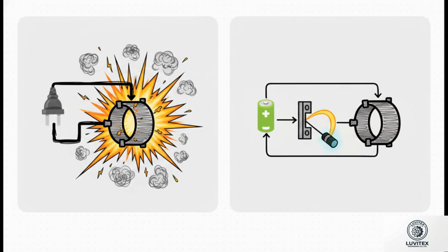And this brilliantly illustrates the real engineering trade-offs between AC and DC coils. AC coils are incredibly fast, but they are highly prone to that fiery inrush burnout we just talked about. DC coils, on the other hand, have a steady, consistent current. This makes them highly resistant to burnout and really great for rapid cycling. But there's always a catch, right? DC coils store energy that can shoot a damaging electrical arc right across your switches when they're turned off. So if you use DC, you have to specifically wire in an extra component to absorb that hit.